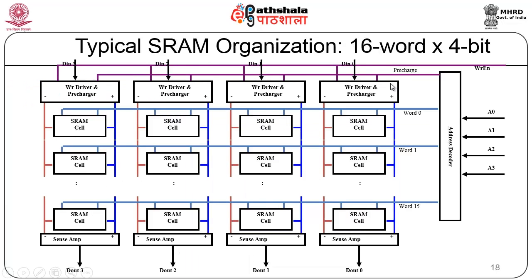But as you can see, because you have 6 transistors making up one basic cell, it consumes space, and that is why your density requirements are not being satisfied by your SRAM. It consumes more space. So, obviously, you can accommodate only a smaller number of basic cells in a given area.